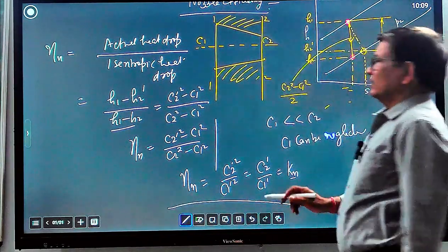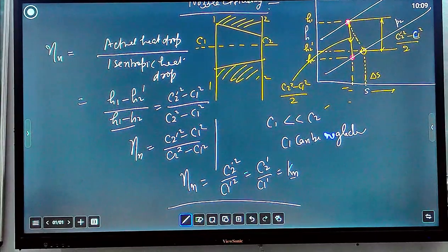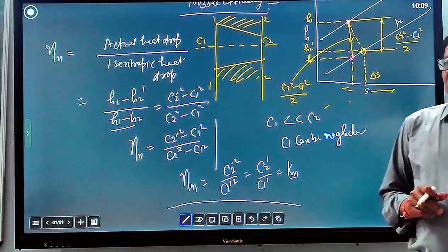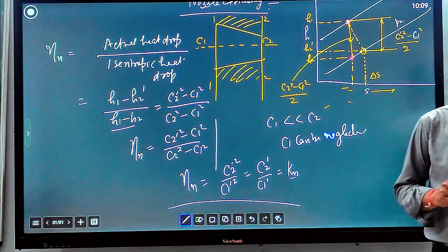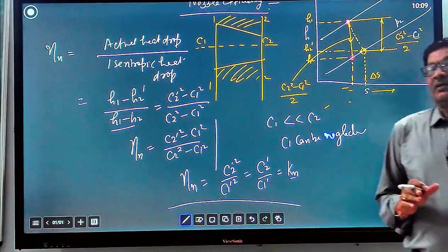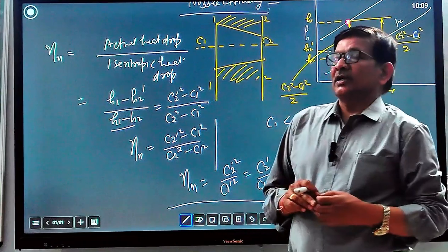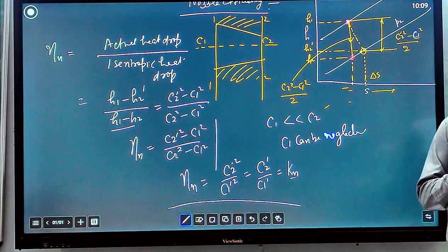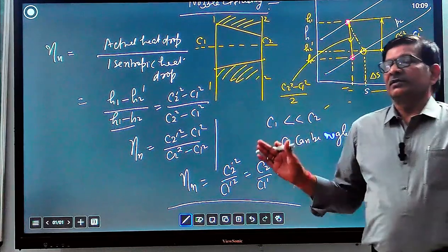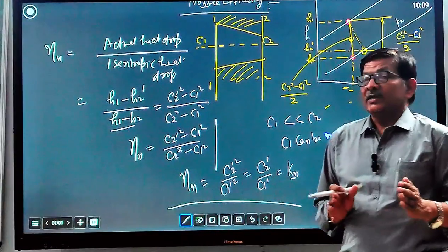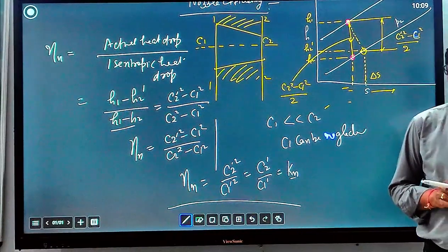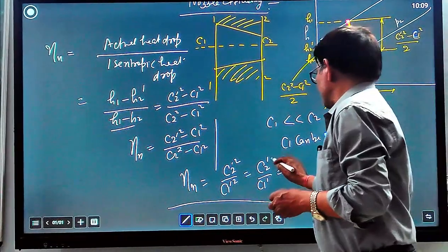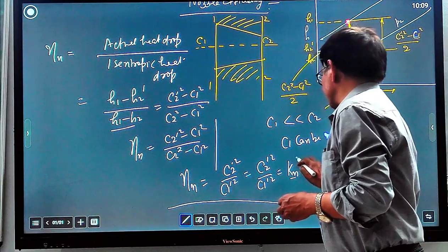So you can see that in a convergent divergent nozzle, in the convergent part, the flow is more secure and you will see a lesser amount of frictional losses. But in the divergent part, where the opening is diverging, there is a greater chance that the flow may separate.